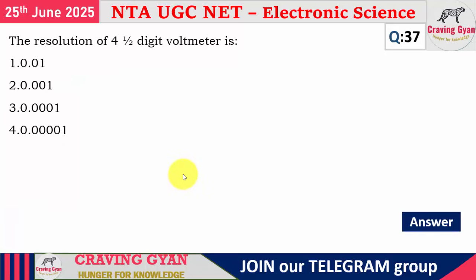37th question. They are asking the resolution of a 4.5 digit voltmeter. What do you mean by 4.5 digit is important. You will have 4 full digits to represent here. Each of these places can take from 0 to 9, whereas this half digit can take either 0 or 1.